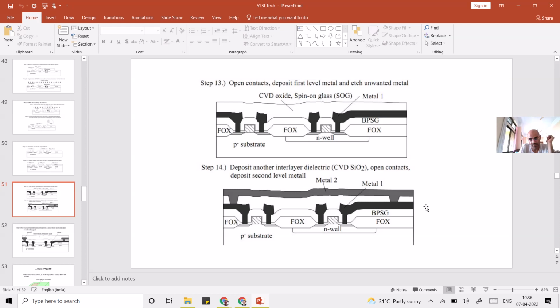The reason is, in this case the interference will be less, because if they are at the same plane, then there will be more interference because the isolation will be less in between the interconnects. So what we do is we make an insulating layer, and over that we grow those long wires, because those long interconnect wires will run throughout the chip. Okay, so they will not be localized, but they will run throughout the chip. So just to protect the device from the interference, we grow these metal layers a little above.